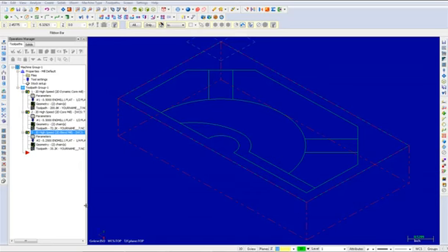In this video, I will show you two different 2D high-speed peel mill toolpaths. A 2D high-speed peel mill toolpath allows for efficient constant climb milling between two selected contours or along a single contour. For single chains, you need to define the width of the cut, otherwise, the width is defined by the area between the two contours.